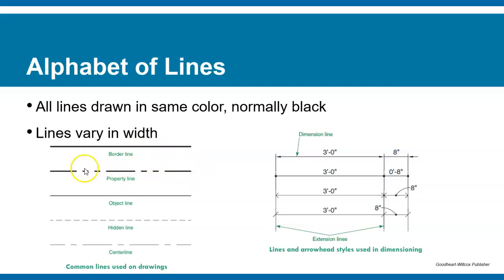And this is typical. And so again, a library of lines to ensure the reader that they know what they're looking at. When you see a solid dash dash and a solid dash solid next to each other, you could get confused. But if you know that the double dash represents the property line and the single dash represents the center line, then in your mind you make sense of those lines, and then you get a better idea of what you're looking at.